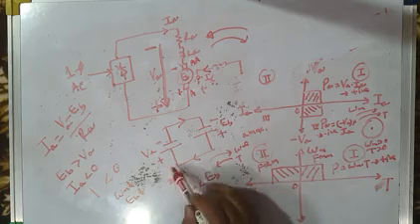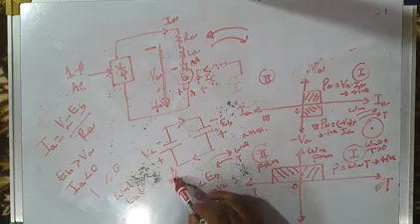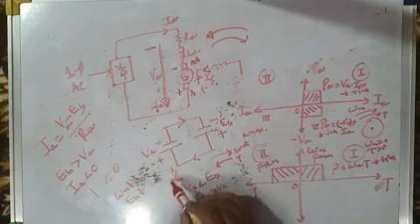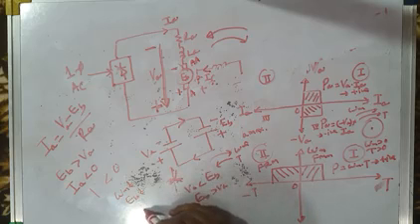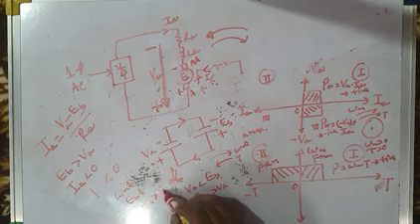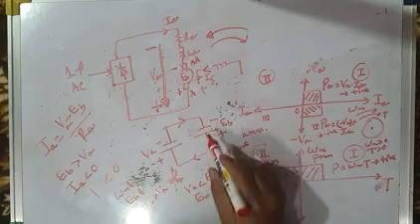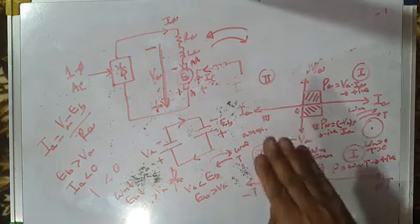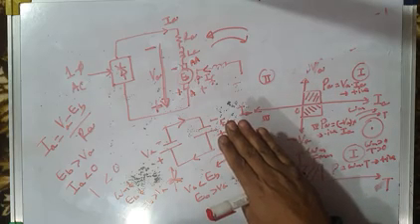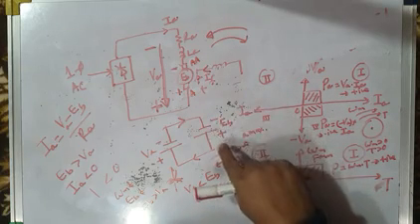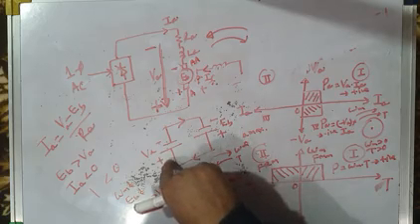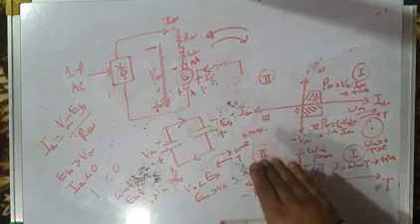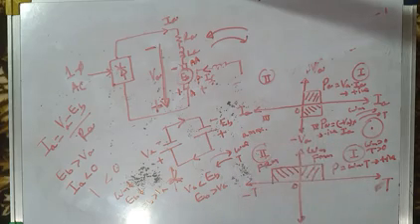So you have firing angle control here. You decrease the delay angle from 180 degrees towards 90 degrees. When you adjust the delay angle, you can always maintain EB greater than VA like this. And as long as EB is greater than VA, the regeneration will take place. Motor will further slow down, speed will further come down, EB will decrease, but you decrease VA simultaneously also, so that you maintain EB greater than VA till the motor finally comes to standstill, it stops.